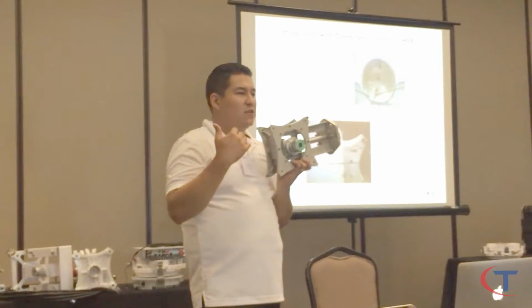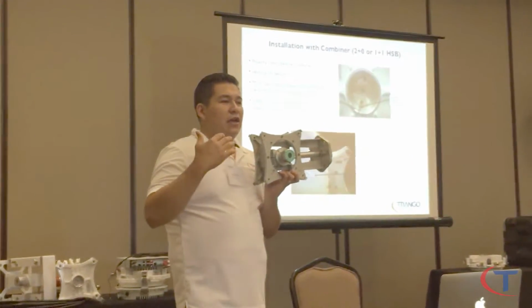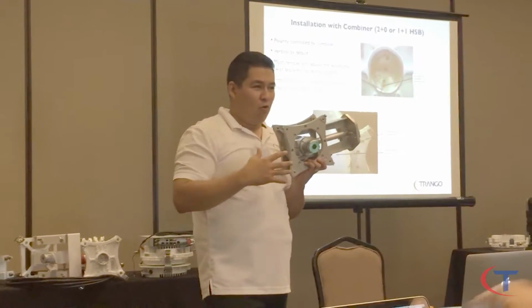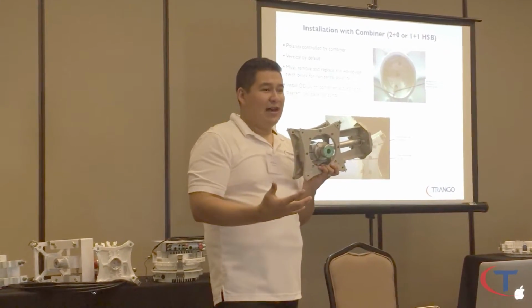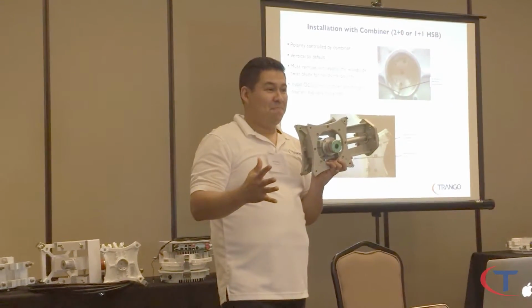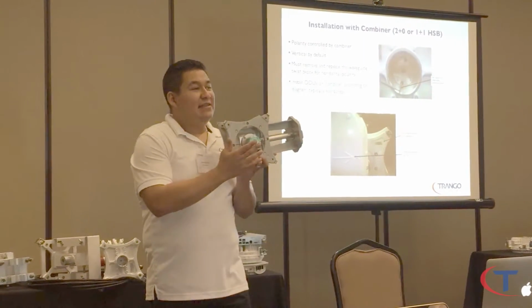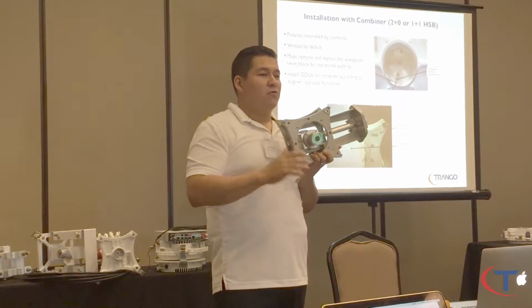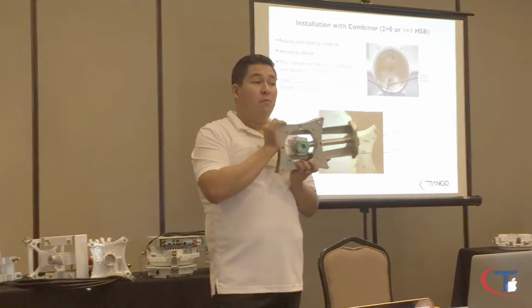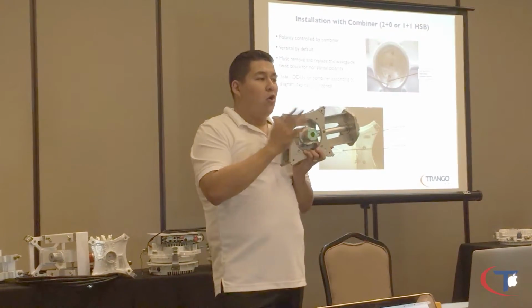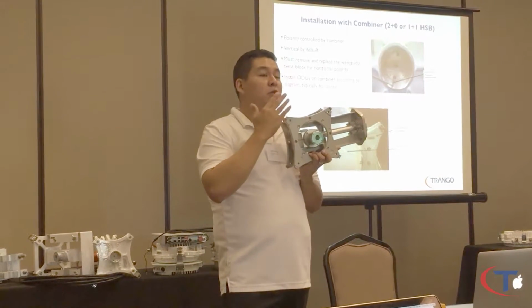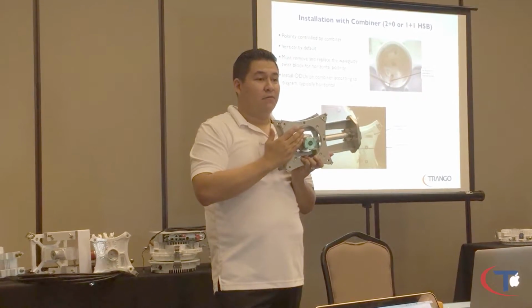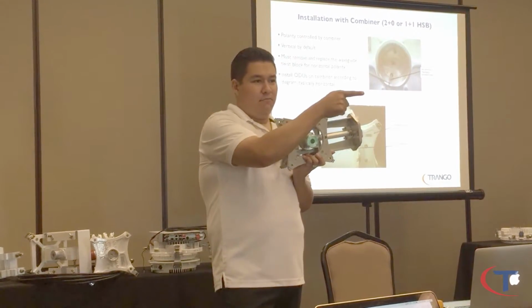And I've had this happen a couple of times to customers. They cross-polarize all four. They get a good RSSI, but nothing locks. Okay? So this happens quite a bit in the field. I'm going to pass it around. And again, remember, rule of thumb: when I'm using a combiner, make sure the ODU matches the internal polarization of the combiner. Like if my slit is like this, make your other slit like this. Correct.